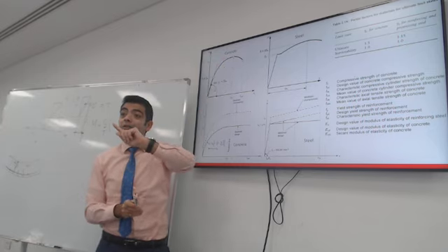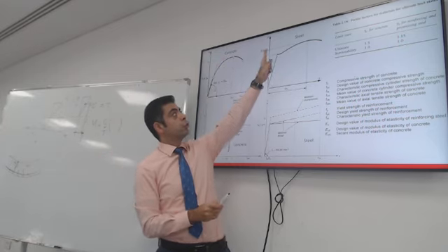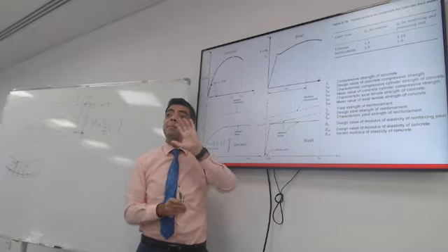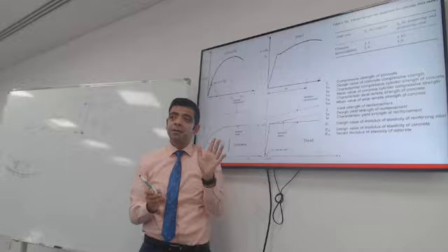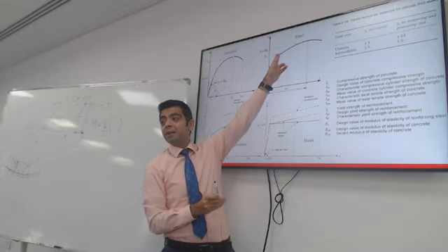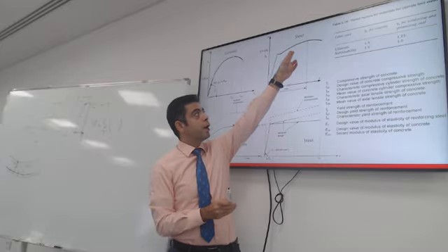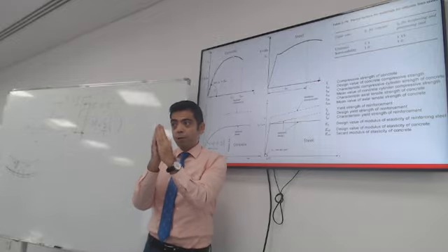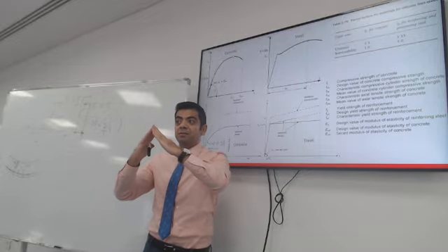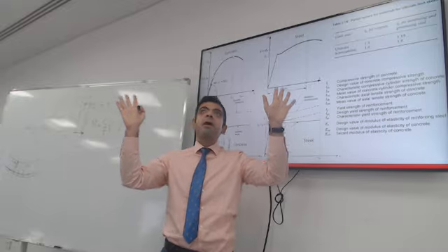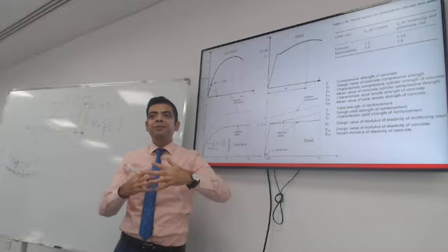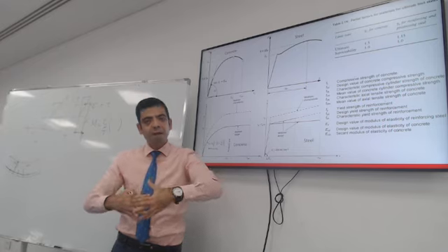You do want steel to reach yield first. The reason why, and that's something brilliant about steel: when it reaches yielding, it will show a lot of deformation before it actually fails. It will show very wide cracks before it gives up on the structure and the roof comes down. So you want that. You want to have a ductile failure.